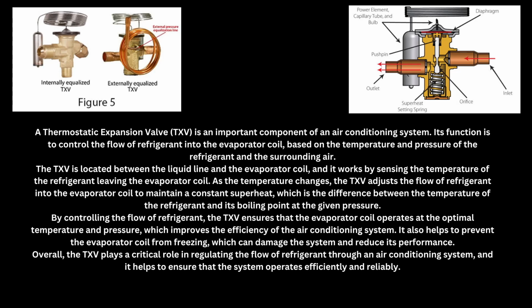spring. Remember I told you that we superheat this? There's where your terminology comes from. You have on the right side your inlet, and on the left side your outlet. So when you're looking at the thermal expansion valve, you have two fittings. And if you take it and stand it up where the diaphragm is pointing upwards, the one on the right is always the inlet valve, and the lowest one is always your outlet valve. So that tells you which way the flow on that thermal expansion valve is designed.